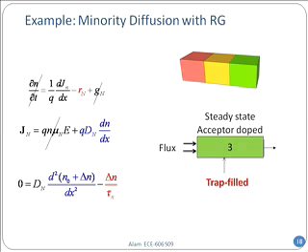The minority carrier recombination, delta n divided by tau n, right? That you remember. Now remember, the various approximations we did, that applies in various cases. Had it been high injection, what would have been this value? Delta n divided by tau sub n plus tau sub p. Remember, I was asking that question, how come in high injection the recombination looks smaller? So under appropriate conditions, you will have to replace it with appropriate expressions for recombination, right?